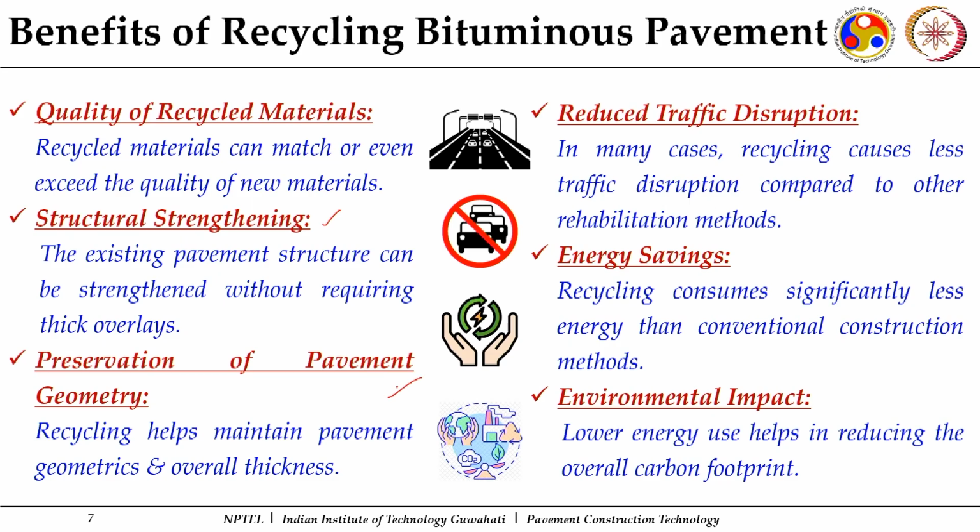Preservation of pavement geometry, this is again a very important concept. What happens if we keep on putting overlays? It will disturb the geometry, the cross section, the geometrical features of the roads, the roadside elements, the height of the median, the height of the shoulders, the drainage, all those aspects, and even on some of the CD structures it will increase the live load like anything. So, we disturb the geometry of the road by putting more and more overlays every time.